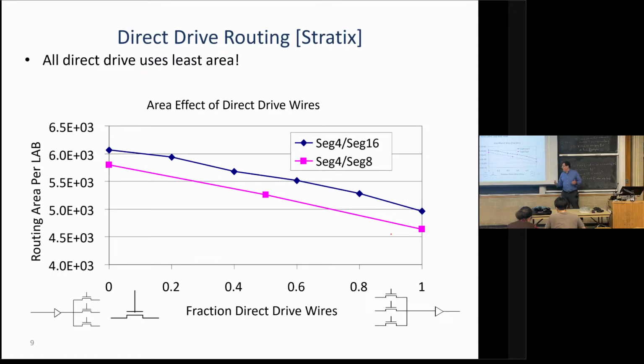So what it means is, well, this length 4, length 8 combination, we didn't really need significantly more routing tracks, so we have a more electrically optimized design that doesn't take as much area. We use small pass transistors. It just cuts area. It cuts it by a lot. Even with the longer wires, where our channel width went up some, the electrical improvements are enough that we still save a lot of area. So it's overall very good.